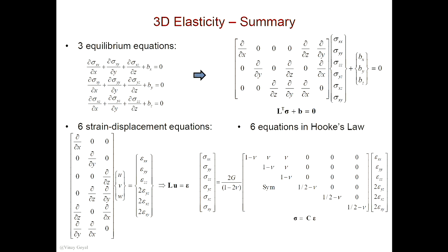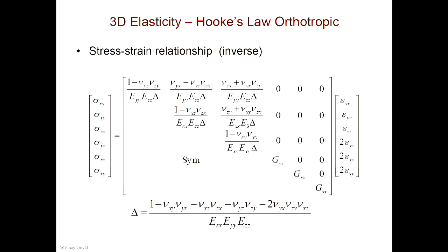We also have this full constitutive behavior for 3D, which is isotropic here, but you can make it composite. You can use a fully populated composite material given here. So if you're working with composites, you can fully populate this, and Abaqus can handle it.